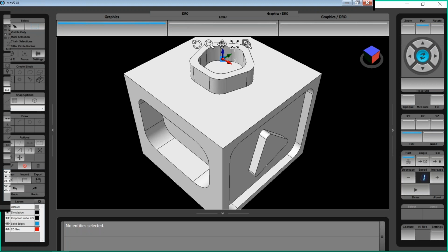So if the part had a Z start of 1 and then it dropped down or raised up, once you created those entities, you could go into the input fields at the bottom center of the screen with those entities selected and set the start and end to Z0 on all of them, and it would put them all on one plane. And then you could use Z start and Z bottom. I know that's pretty cumbersome, but that would be the workaround until we can implement something different.